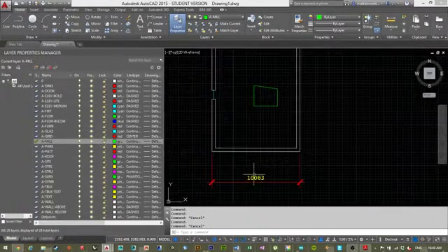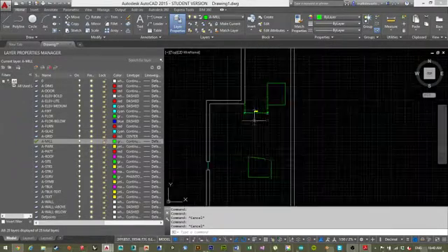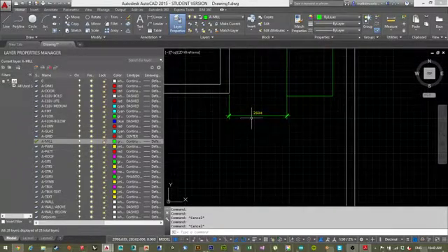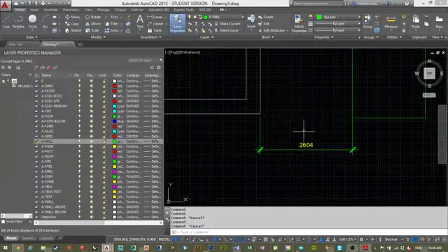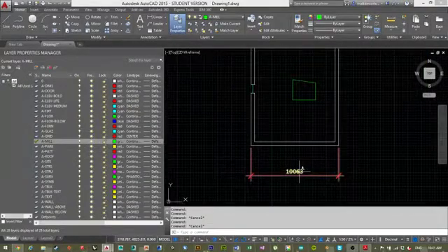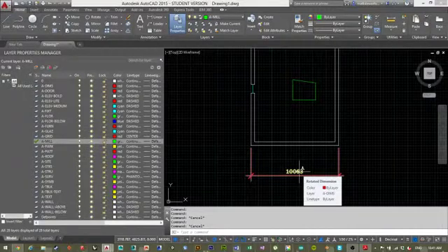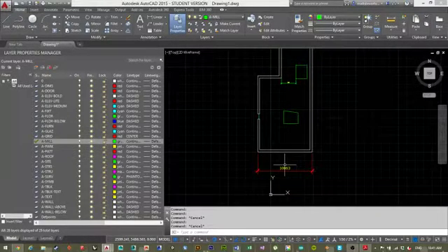You can even see this text here is bigger than this text, because this one knows it's going to go in at 1 to 50. The text will have to be smaller to be 2 millimeters high on that page. This can get confusing, but since the building is going to be smaller in this view, to be 2 millimeters high the text is actually bigger.